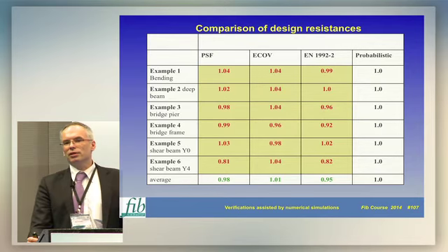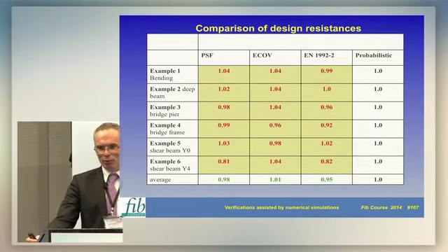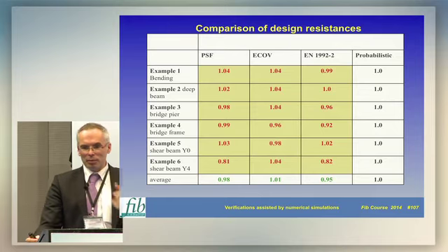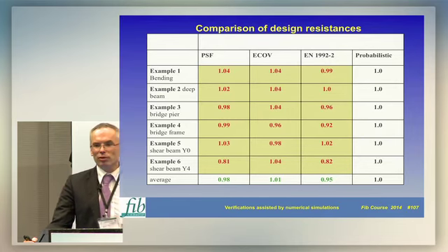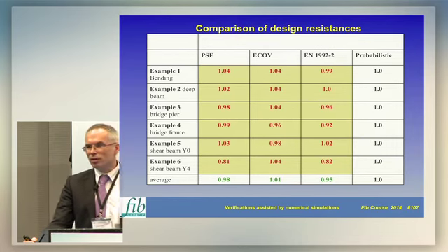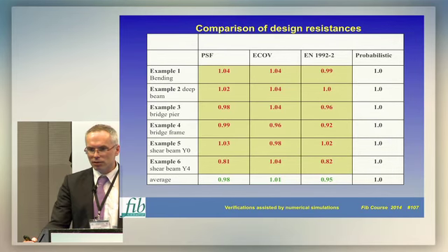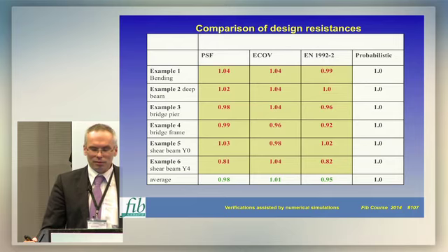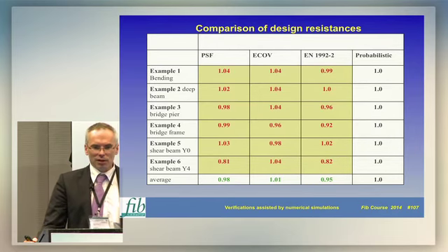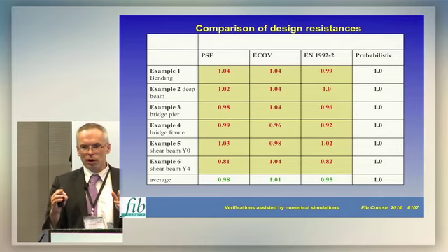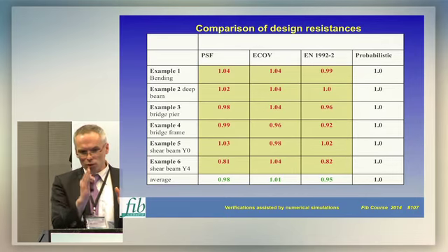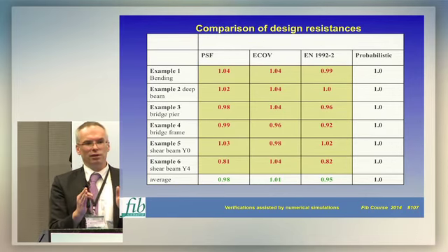Also, what I want to point out is it very much depends how you make the probabilistic approach. Because as it was pointed out by previous speakers, if you do probabilistic analysis, it very much depends what kind of distribution you consider for the material parameters. So when developing the probabilistic approach, what we did is that when defining the statistical distribution for instance, for the compressive strength, we used normal distribution, which kind of, I think, is used in the code, and we selected it such that it goes through the mean and it goes through the characteristic strength.